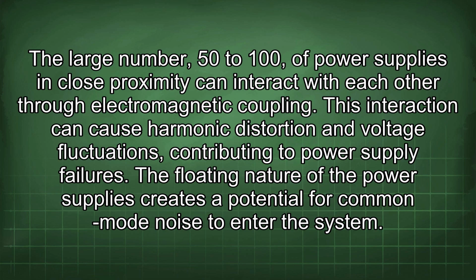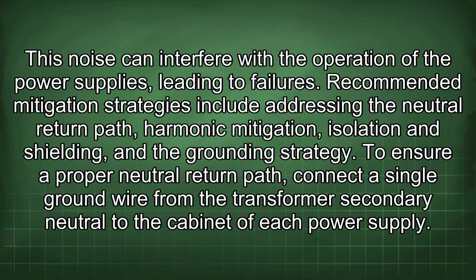The floating nature of the power supplies creates a potential for common mode noise to enter the system. This noise can interfere with the operation of the power supplies, leading to failures. Recommended mitigation strategies include addressing the neutral return path, harmonic mitigation, isolation and shielding, and the grounding strategy. To ensure a proper neutral return path, connect a single ground wire from the transformer secondary neutral to the cabinet